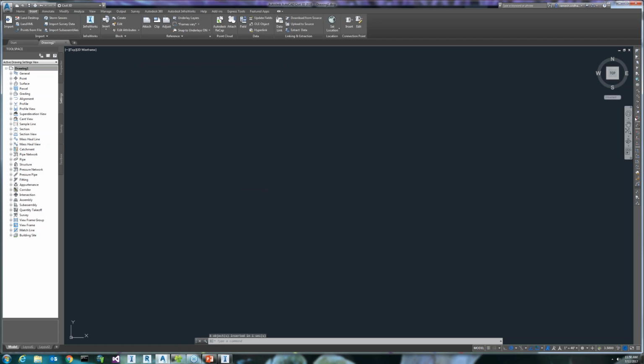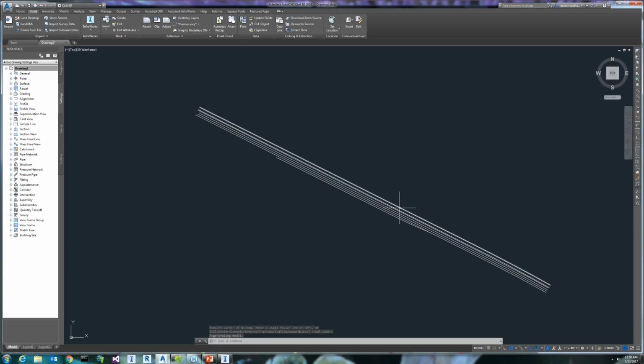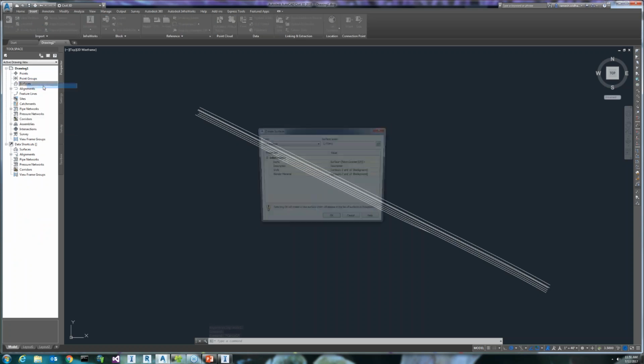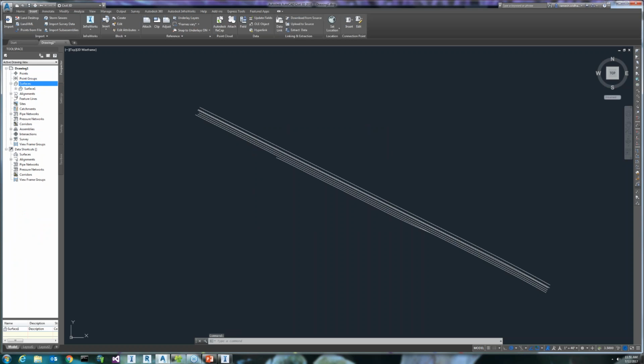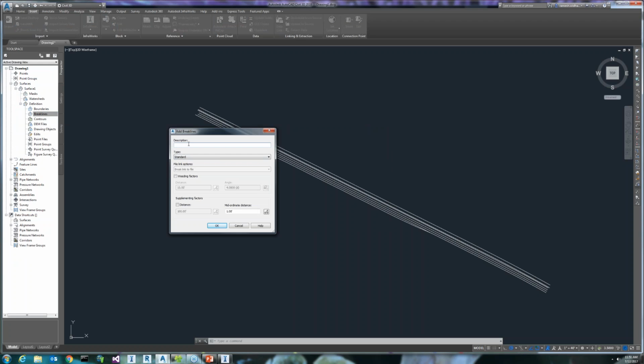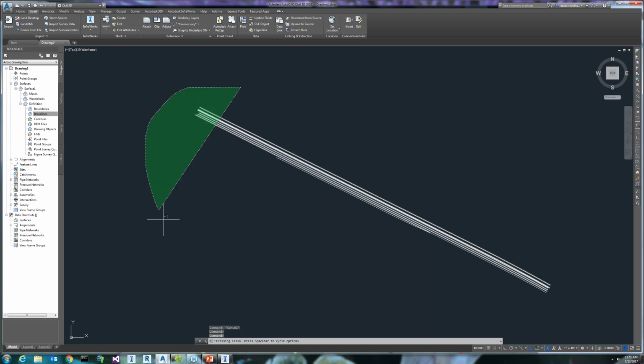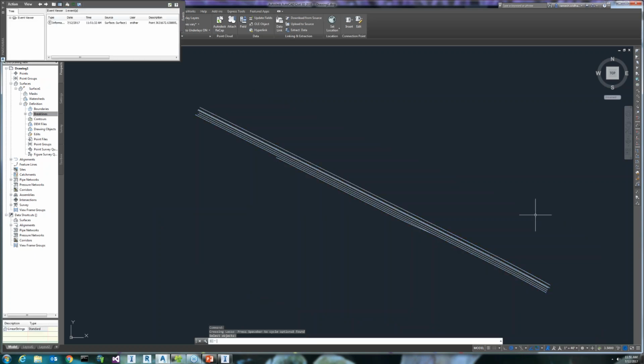And if I zoom to extents, that's all my linear features here, and each of them carries all the details. So if you want to create a surface, which the customers might know already, I can just create a new surface and add this as a breakline. I'm going to add it. So this is where I'm just going to call it linear strings, and I want vertex spacing, let's say every 5 feet in this case. So this is where you can actually do that part. I was answering one of the questions, and then go ahead and select these guys.